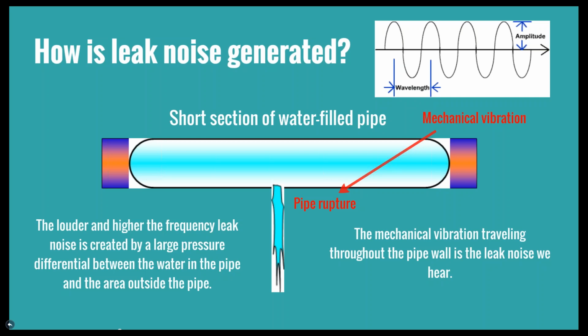Again, as I mentioned, depending on the size of a leak or whether it's a joint leaking, and even the backfill around the pipe, that will impact how the noise is generated. And as I mentioned, a lot of technology and algorithms are in place with many of the technologies out there to help filter through this type of information and provide more accurate data with different pieces of equipment, whether it's loggers or correlators, to identify where the leak is specifically. Next one, Noah.